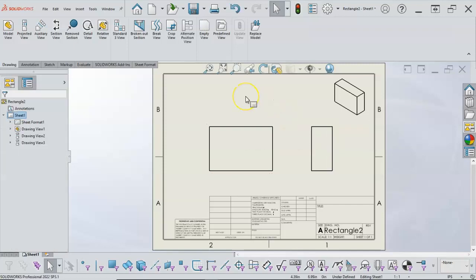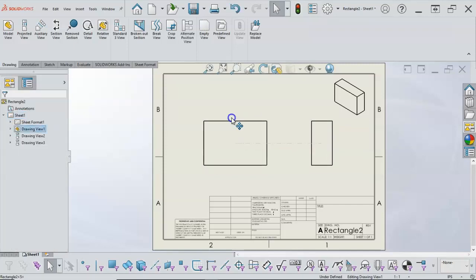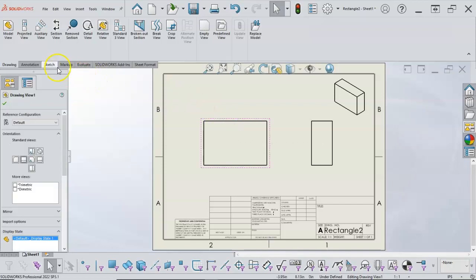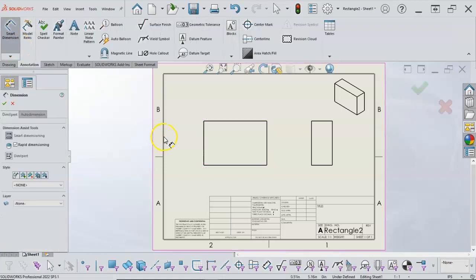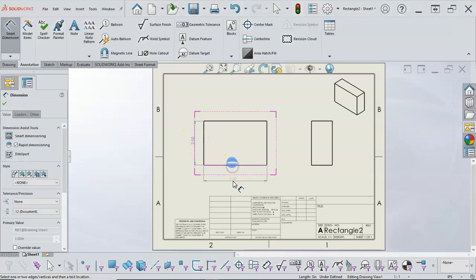So again, just getting into the process, seeing how these drawings connect to the part. The drawing does not consume the part. It references it. And so we're going to, okay, so there's the rapid dimensioning. If those get too annoying, those little boxes when they pop up are location and also bring up some of the parameters for the dimension.